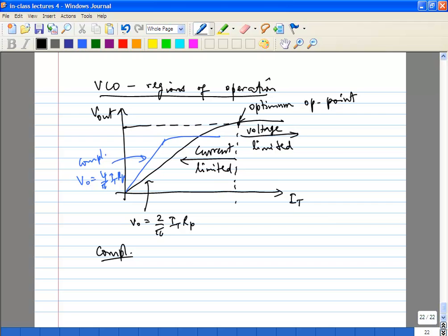this voltage in an NMOS only transistor, the bias point is VDD, so the maximum it can swing is all the way down to 0 and all the way up to 2 VDD. So swing is going to be VDD, maximum amplitude, whereas here, maximum amplitude is going to be 2 VDD, maximum swing, whereas here, because you have VDD swing on either side, so you're going to have 2 VDD differential, whereas on this guy, you're actually limited by the VD sat of both the NMOS and the PMOS, you can never swing above VDD. So that is something you have to keep in mind.